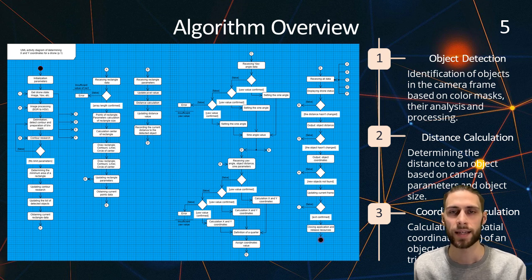Based on the initialization of the camera parameters, as well as the dynamic change in the pixel value of the target object, the distance to it is determined during the flight. Moreover, the work is carried out precisely with the center of mass of the detected object, since its height may be inaccurate due to reflections on the surface, being hidden or covered by another object, as well as due to poor lighting, shadows, or perspective distortions caused by the camera angle.